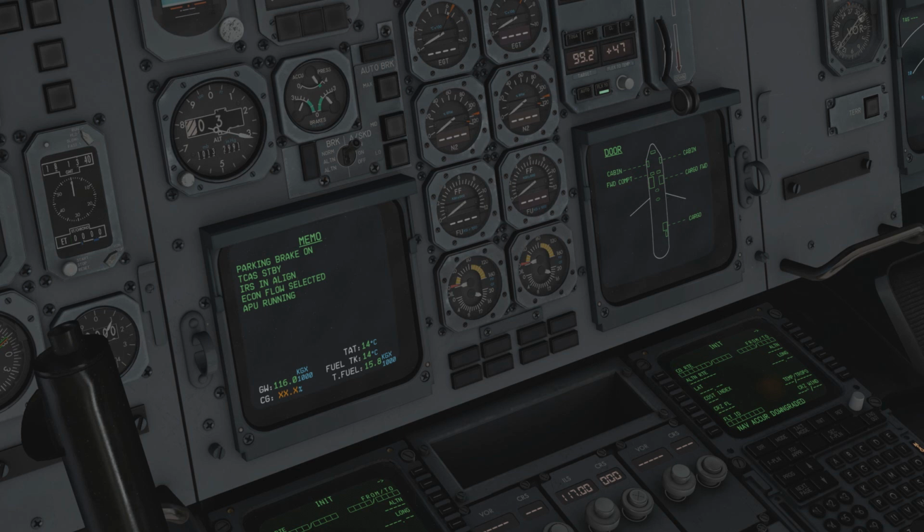So a lot of these images are displayed by things called SGUs. They stand for Signal Generator Units. And on modern aircraft, or modern Airbus aircraft, again, a phrase we're going to hear often, they're called DMCs, Display Management Computers, I think. Anyway, we'll stick with SGU. So SGU is what they're called on the A300, and they basically make images. They make the images, and they're limited in some fashion, but pretty advanced in others. So how do we interact with these screens? Well, we interact with them with a panel called the ECP, the Ecam control panel.